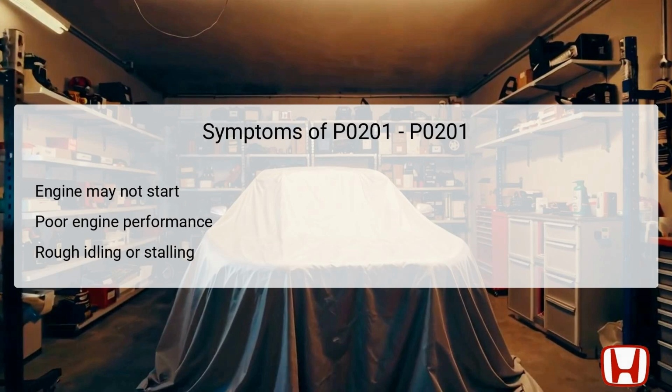You might also notice rough idling or stalling when the engine is running, which indicates that the injector is malfunctioning and disrupting the fuel-air mixture necessary for smooth engine operation. Recognizing these symptoms assists technicians in understanding the urgency and the potential extent of the repairs needed, as well as serving as diagnostic parameters during troubleshooting.